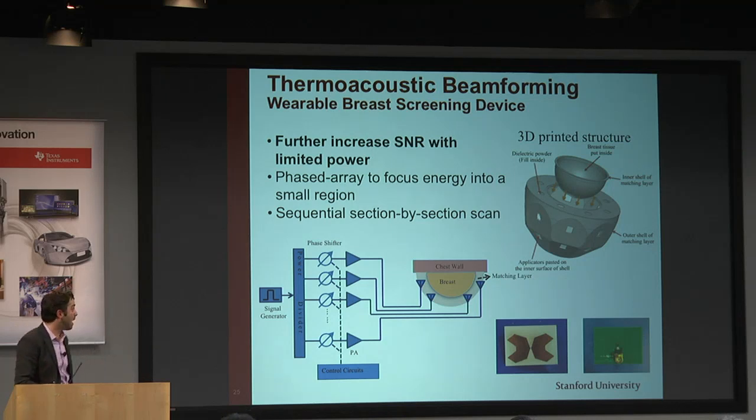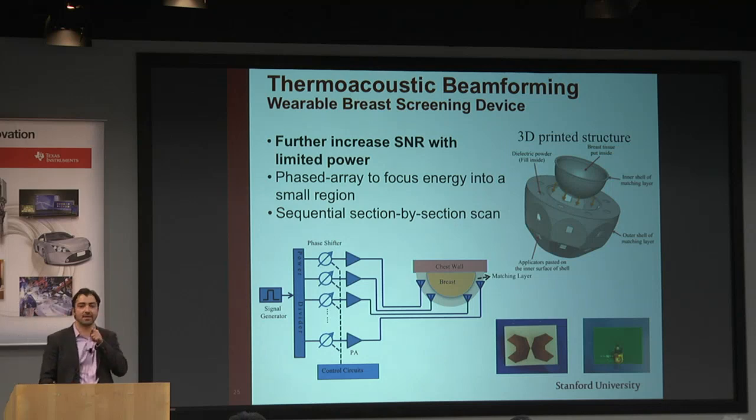Now, there's actually a side benefit. It's a subtle point, but it's actually more important. If you only have one antenna and you put it next to tissue and you excite it, the hottest point, the SAR limit, the thermal regulation FDA limit, is going to be set by the point at the surface. So the deeper you go, the energy dies exponentially with the losses in tissue. Now I have 10 antennas around, I can make the hottest point be my target point instead of being the surface. That's a huge improvement. It's a subtle point, but that's actually what we win by using an array.